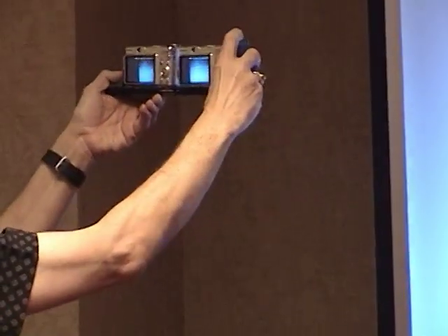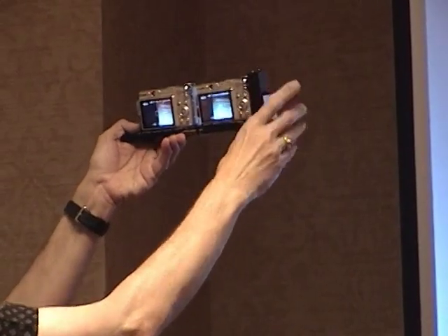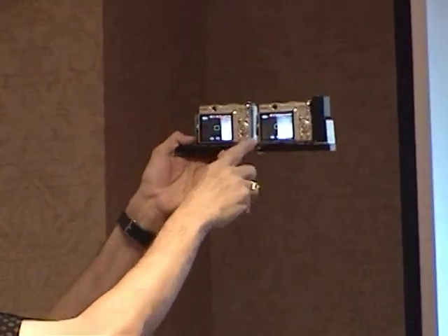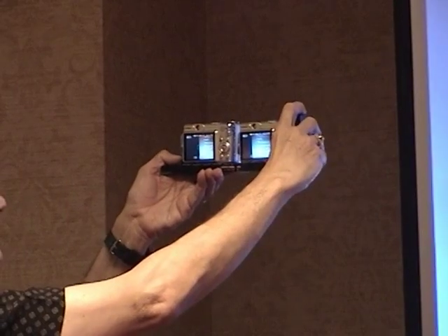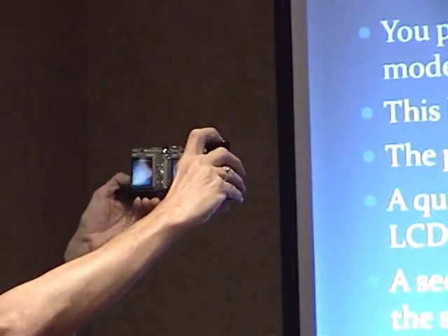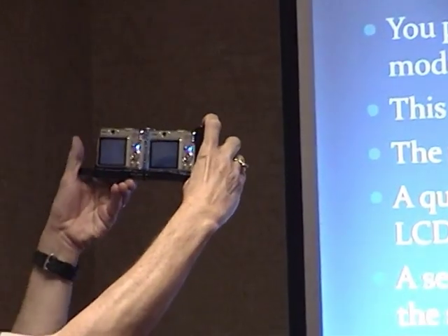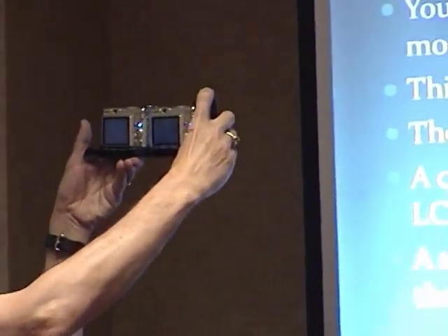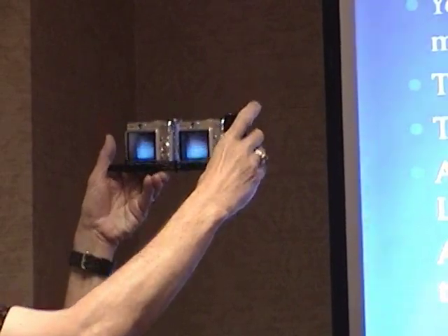When you press this button the first time, you heard the beeps from the camera. It's now in focus mode, and it set things up. When I press it again and release it, it took the photo. If you don't want to do that, you can hold the camera up, press it down, leave it down until both screens go blank, because it's not doing that update LCD routine, and when you release it, it takes the photo. If you forget that you have to wait for the release, if you get in a hurry, then it will get out of sync, and you'll start thinking that something is broken. Really, it's operator error.